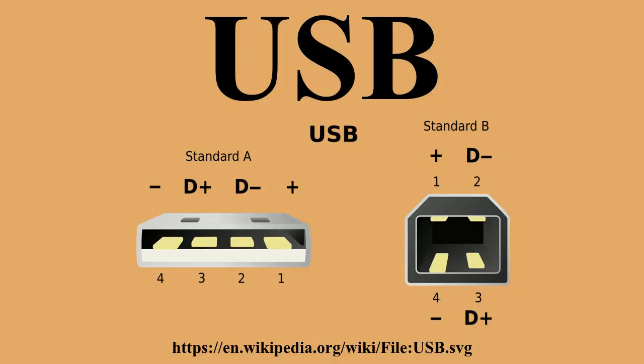Converters also exist that connect PS2 keyboards and mice to a USB port. These devices present HID endpoints to the system and use a microcontroller to perform bidirectional data translation between the two standards. Device firmware upgrade. Device firmware upgrade is a vendor and device-independent mechanism for upgrading the firmware of USB devices with improved versions provided by the manufacturers, offering a way for firmware bug fixes to be deployed.